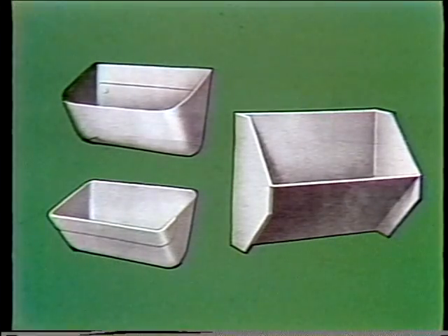On the chain type elevator, the attachment chain is used. There are many styles of the attachment chain, and we simply bolt a bucket onto the chain. Here are several different types of standard buckets. Now, we can use either single chain, where the chain runs down the center of the bucket, or it may be double chain, where a chain is bolted to each end of the bucket.